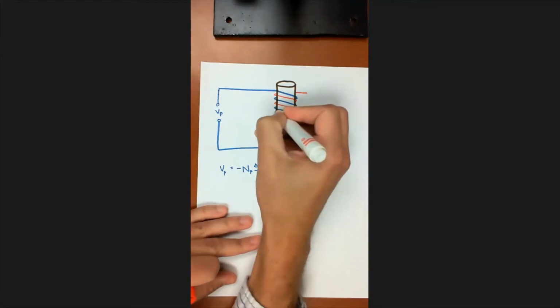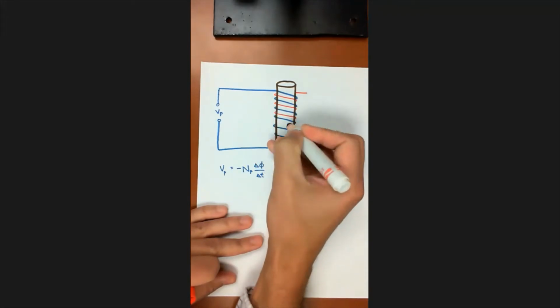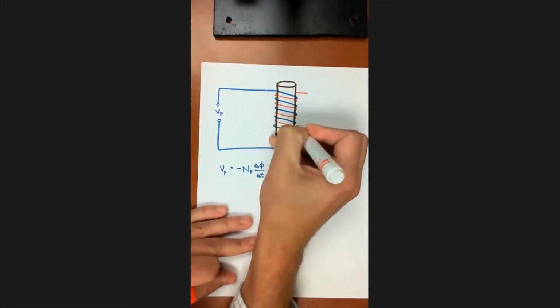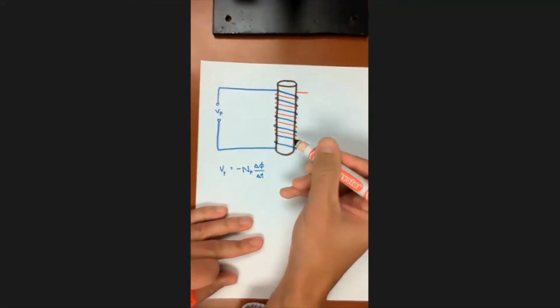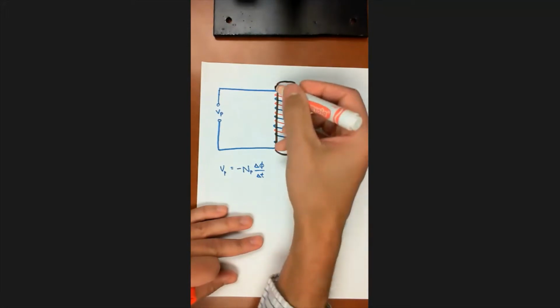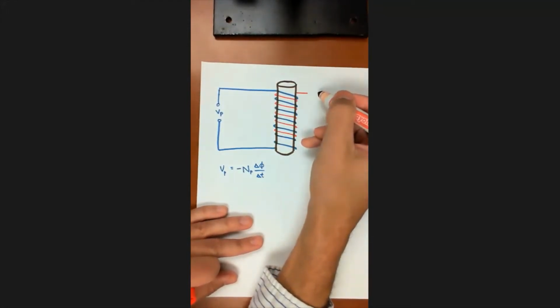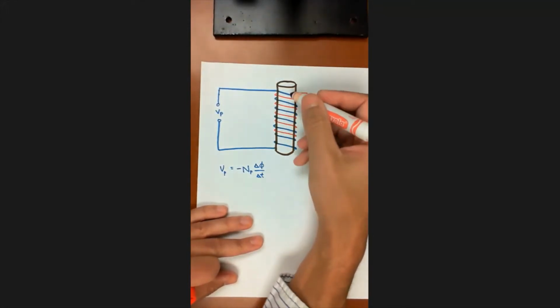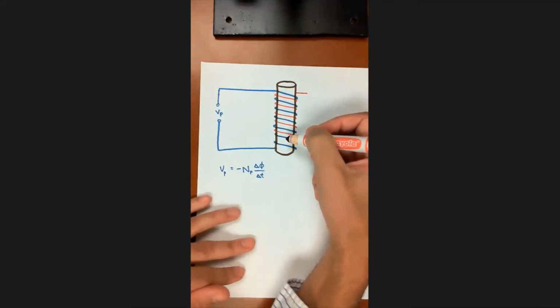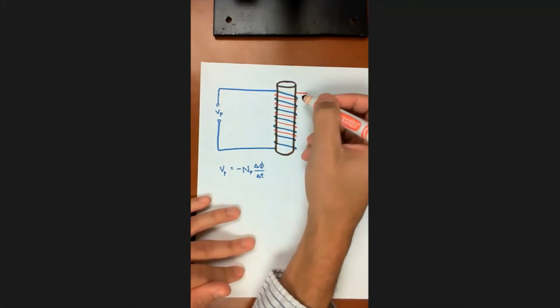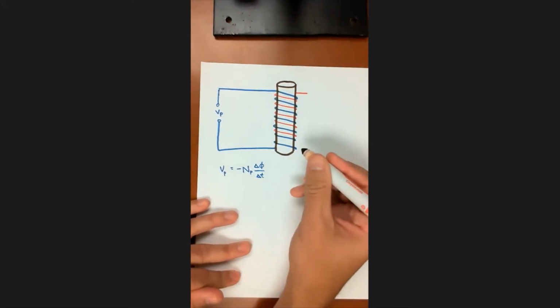And remember, each of these wires is magnet wire, which means it has a thin layer of insulation on the outside of the wire. So there's going to be no electrical conduction between the blue wires and the red wires. First of all, I'm drawing them separated. In real life, they wouldn't be physically separated, but they would not be electrically conducting from one to the other because they have insulation on the outside of the wires.